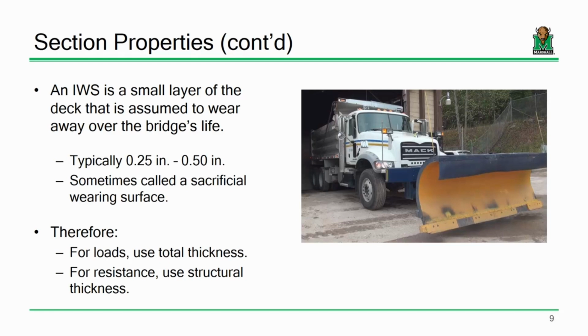Okay? And there's a number of reasons. Just general wear and tear, that's a big reason. You know, the truck scraping the snow and the ice off the bridge, that tends to wear the concrete out over time. So what'll happen is we'll want to make a delineation between how much concrete we're actually considering for capacity and how much concrete was there when it was cast.